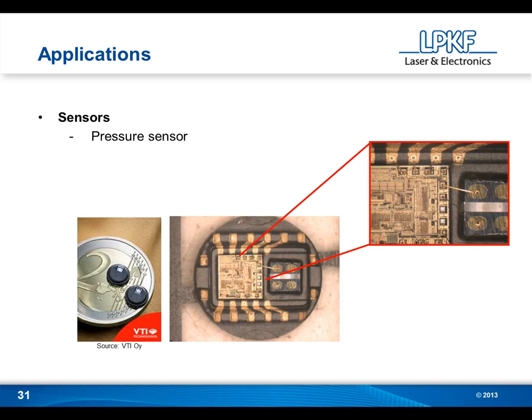And then Stefan, talk about the material this is made from and the temperature constraints because of that. Yeah, that's a good question, Jane. This particular part is being used later on in a mass production environment. So basically, they're sold as bulk parts and being used in any kind of soldering environment. So in order to accomplish this, of course, it's important that the plastic housing used for this particular part is compatible with most standard reflow soldering technologies, including, of course, lead-free applications.